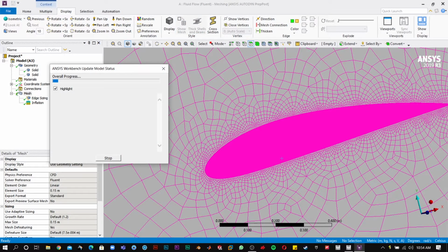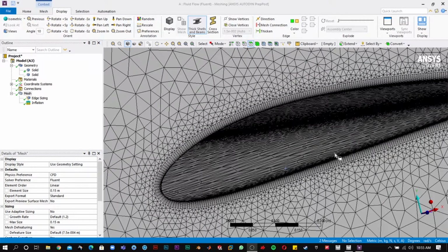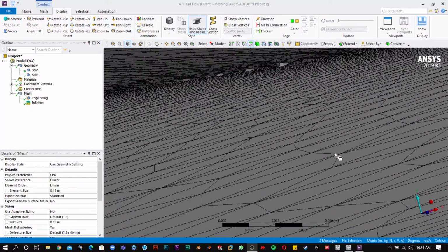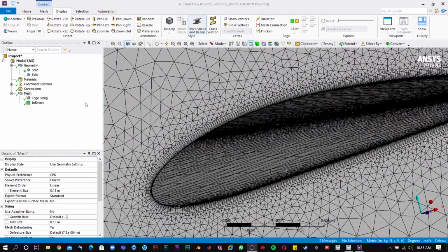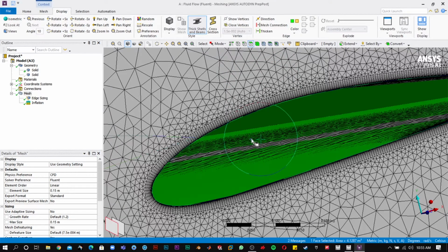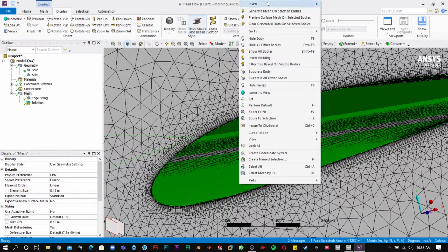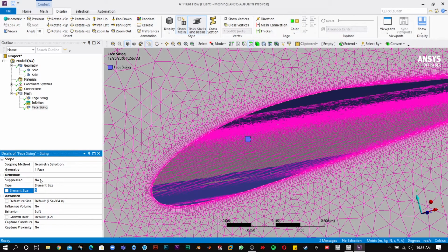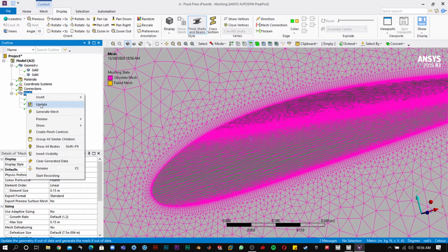So as you can see, the mesh has now become an unstructured one on the inside surface. Let me just change the angle. First, let me change the sizing of the internals. It will be 0.01, and update the mesh. All right.